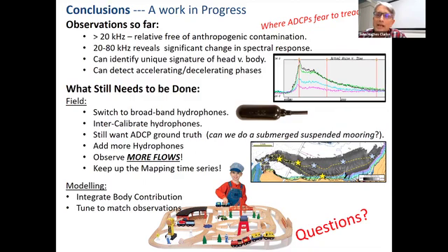But we should be able, if we can see a body pass, we can listen to the body and we can see, is the intensity increasing or decreasing? That tells us potentially how much is in suspension. That might be a little bit too optimistic. I would like to say we can get the grain size, but one of the conclusions, particularly of Matt Hatcher and Alex Hay, was the spectra were flat, and it's when real grain sizes are not that well sorted. But we don't know. But potentially, if we have enough of these and we instrument more active flows, maybe we can get there. That's fascinating.